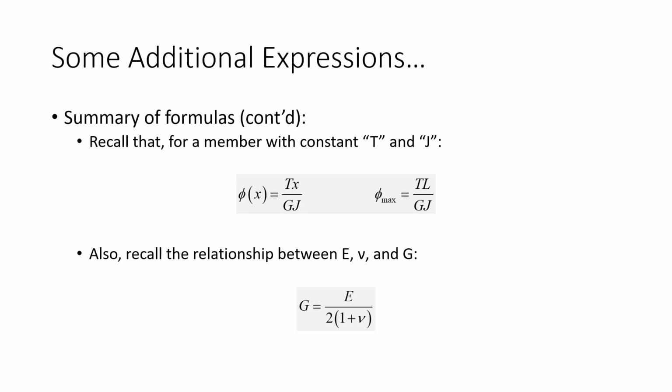And one of the things that you learn is that you could compute just about every elastic material property that you need for real deal stress and strain analysis with only two numbers, E and Poisson's ratio. Everything else is a function of those two in the elastic range. So, for example, a lot of times on torsion problems, I might just give you E and nu, but you need G because G is the shear modulus that relates shear stresses to shear strains. That is easy to compute. It is just E divided by the quantity of 2 times 1 plus nu. It's really easy to do. I'm just telling you that now so that you have that. We're actually going to do that for our first example.